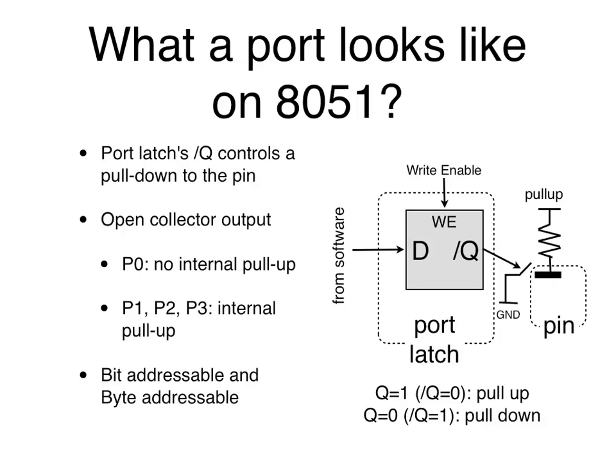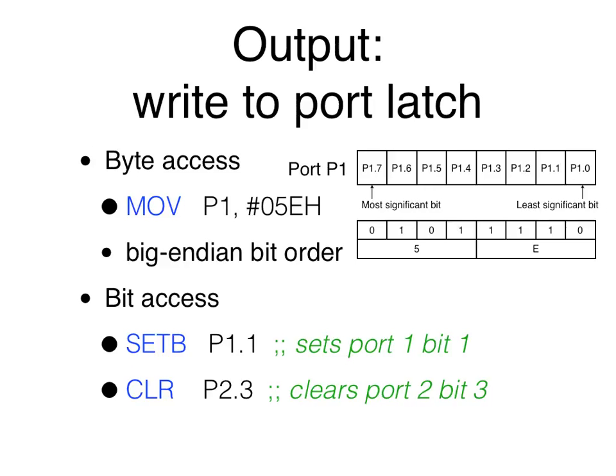So anyway, by setting the D value to 1, it leaves the switch disconnected, and that means it's pulled up, right? Because it's controlled by the complementary or inverted signal of Q. By setting D to 0, that's like pressing the button, right? Because Q bar is now 1, and that establishes a connection to ground, and that pulls it down. Okay. Now, keeping that concept in mind, we can see some examples.